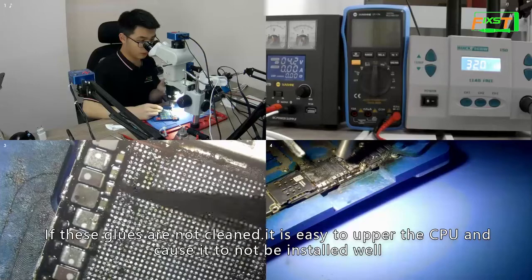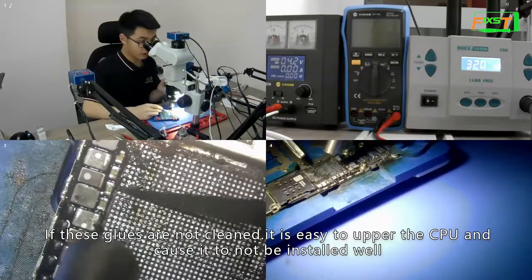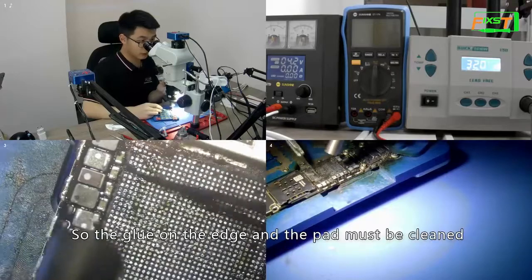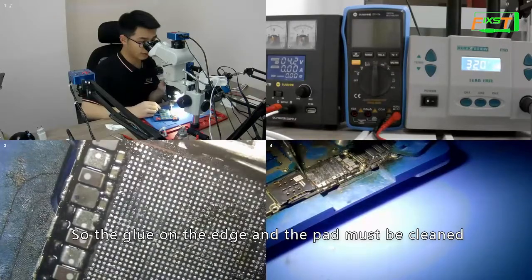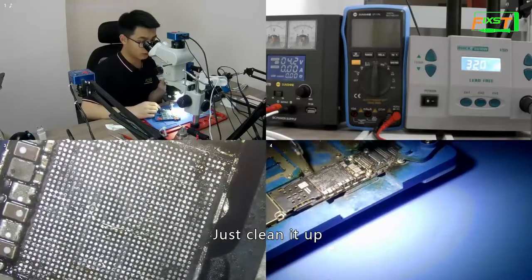If this glue is not cleaned off, it is easy to affect the CPU and cause it not to be installed well. So the glue on the edge and the pad must be cleaned. Just clean it up.